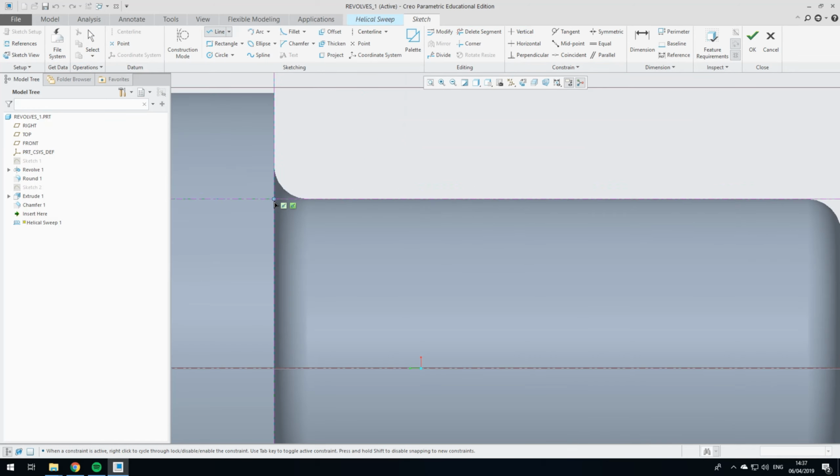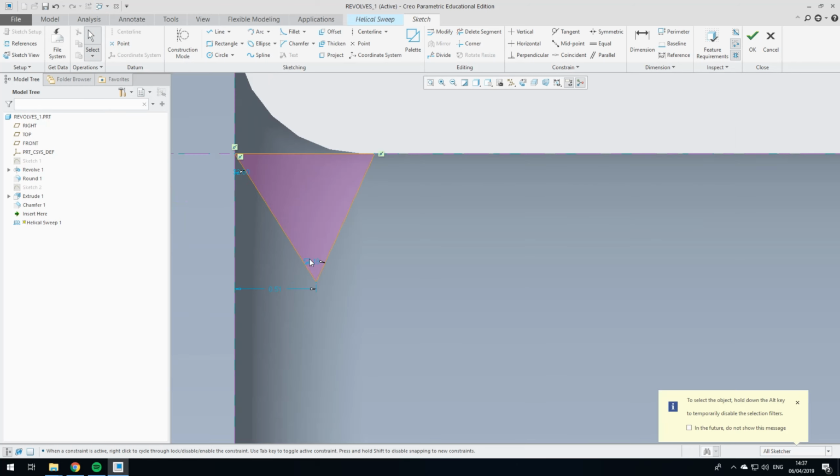And what we'll have here is where the thread started here. We'll draw a triangle because that's what the profile of a cutout in a bolt looks like. And we've sketched it roughly, and now we will add some dimensions. So we know that obviously it's going to be an equilateral triangle in here, so I've dimensioned one side, and I'm going to come and use the constraints.